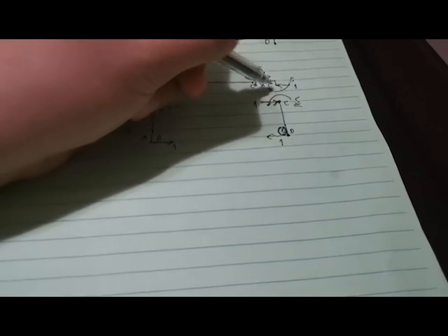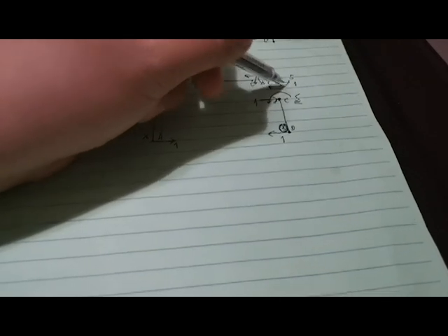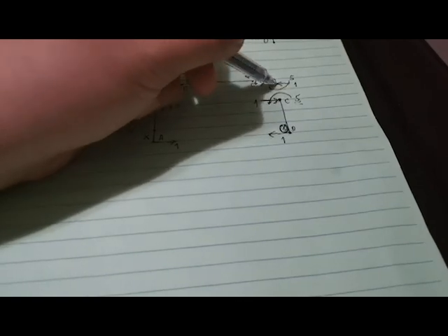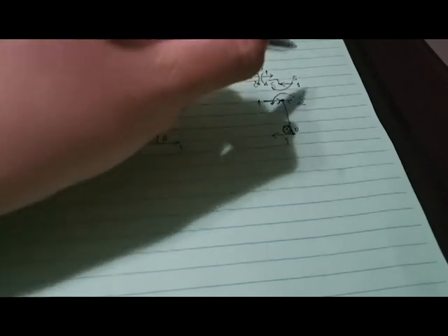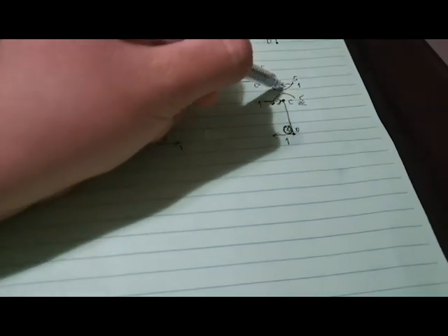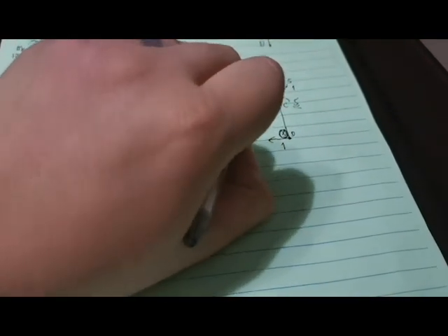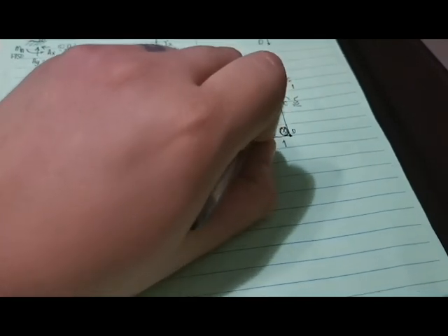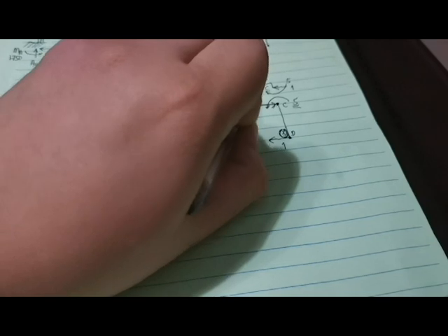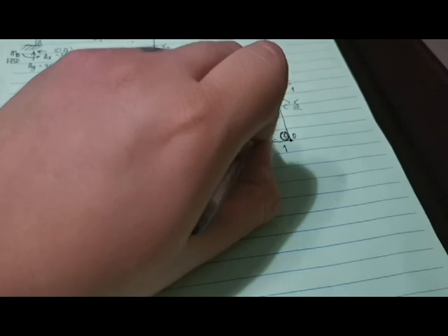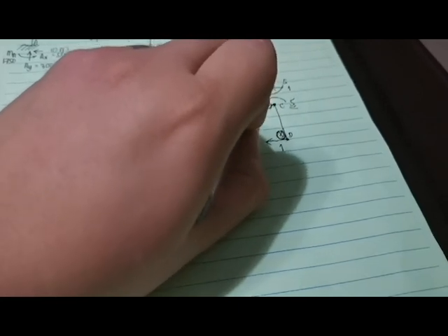Therefore, at joint C, a very small distance going to D, we have a clockwise moment of 5. And then also we have an opposite of 1, so this is going to the right, 1 kilonewton. So we have 1 kilonewton going to the left here, a very small distance from joint C going to joint D. For joint C going to joint B, at a very small distance, if this is 5 kilonewton meter clockwise, we have a 5 kilonewton meter counterclockwise here. If we have a 1 kilonewton load going to the left here, we have a 1 kilonewton going to the right.